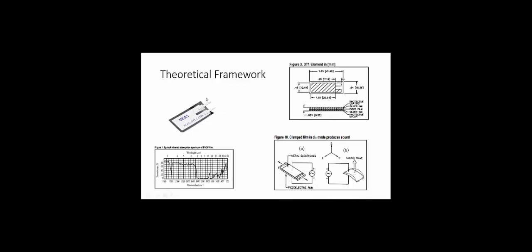This is a piezo element, a very thin film, a very thin plaque, that when it bends is going to give out some voltage. Well, not a very good signal, but it gives this analog signal. When this vibrates, we're going to pass it to a comparator.